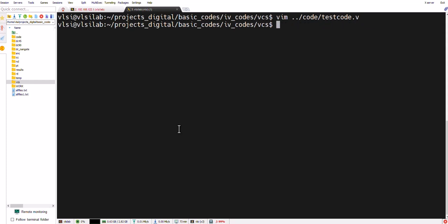In the command prompt we can go in that way, or you can use Tcl files or makefiles. I just created one makefile which collaboratively takes the inputs we require, like the simulation executable, the command for VCS, and the flags; everything is listed in that makefile. You just overview that.